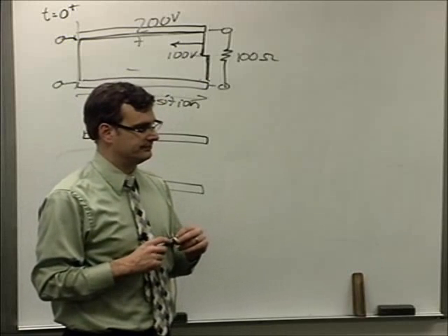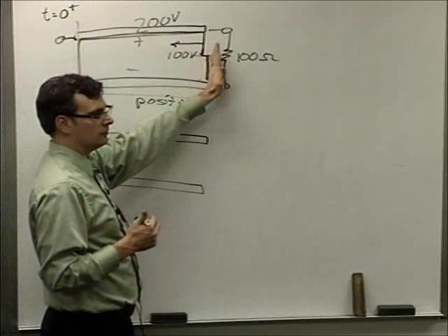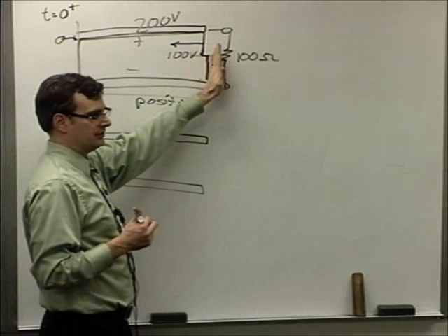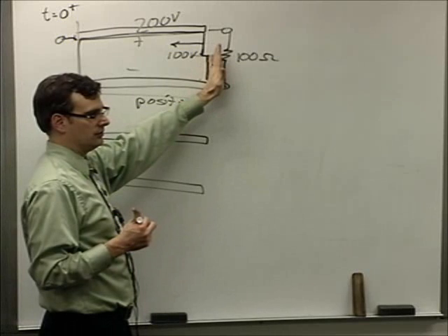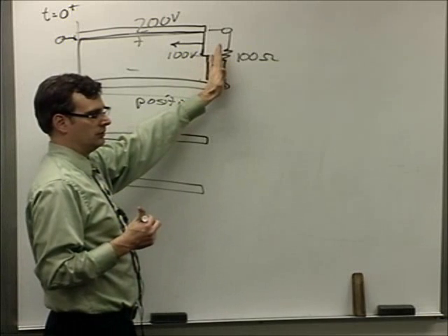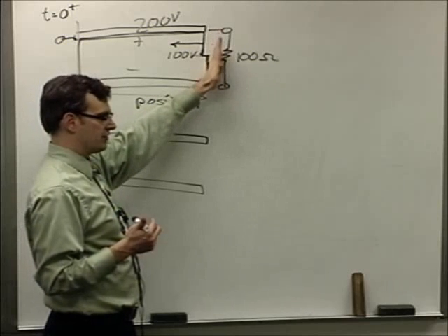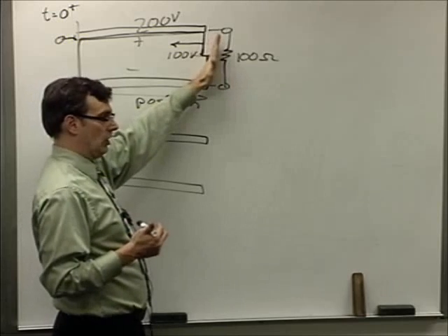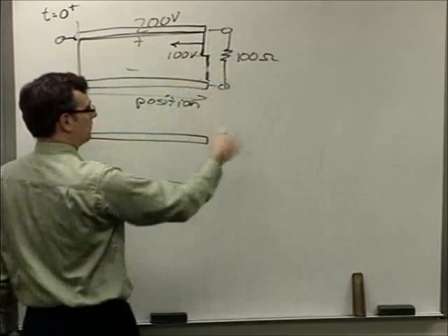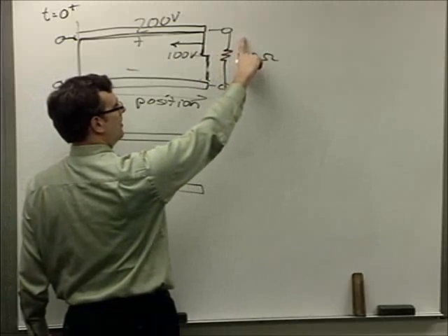That's exactly right. Voltage was being transferred to each other just through the open circuit. Okay, so with this example, we have reflection. I'm just confused how it doesn't go through the resistance and come across the bottom and just do the 100 cycle. Remember, now that the resistance is there, the reflection coefficient is 0. So basically 1 plus 0 is the total times the forward propagating wave, 100 volts, that is going to show up across the load.